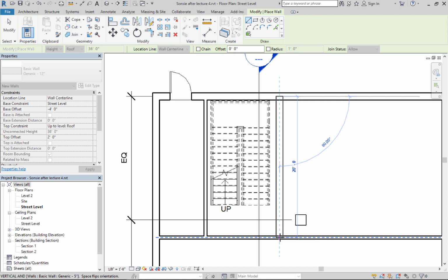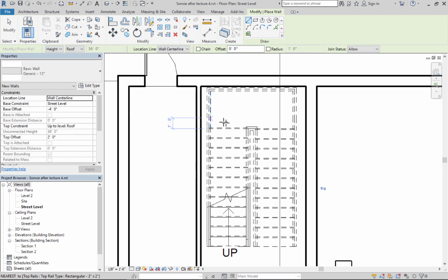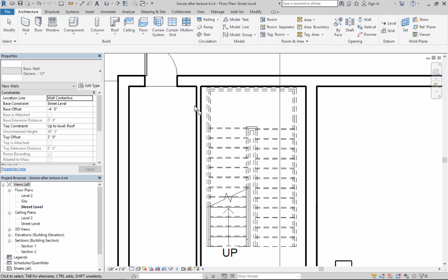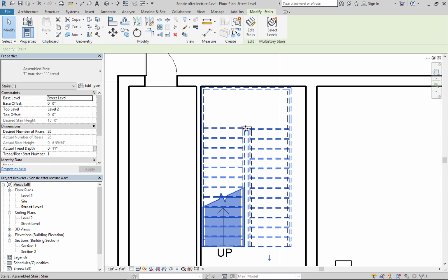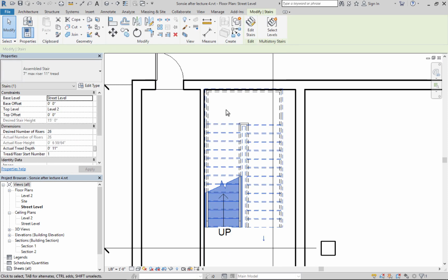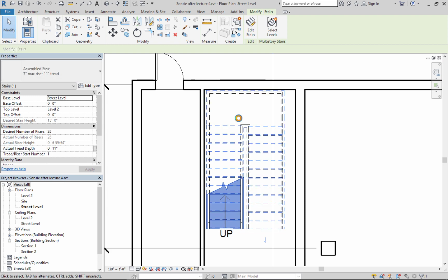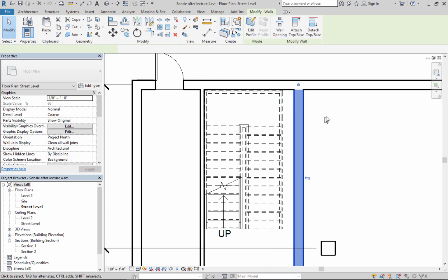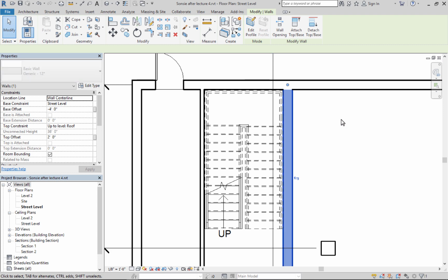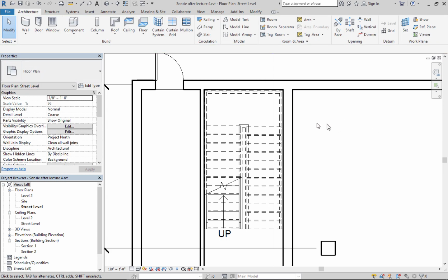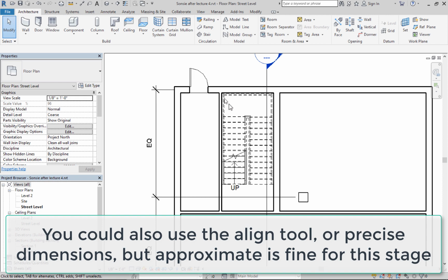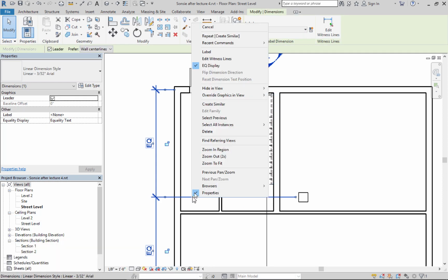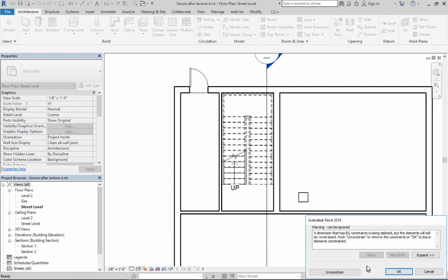And again, when you go and draw your walls, as we saw earlier, using these dashed lines will heal the walls. Now, finally, you can absolutely be super precise with these stairs. In this case, because really we're just getting these in as a design element, I'm just going to nudge these walls over to make them fit. All right. And some doors would be nice, wouldn't they? But before we put in a door, let me just delete this dimension here.